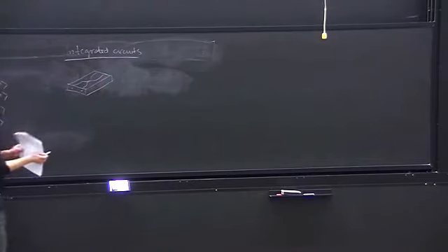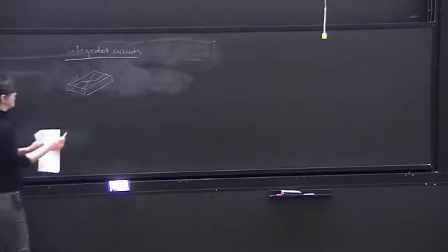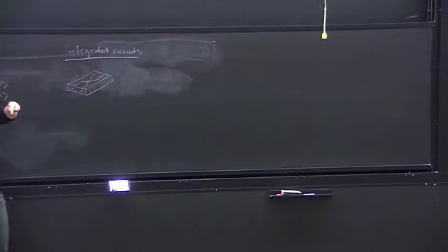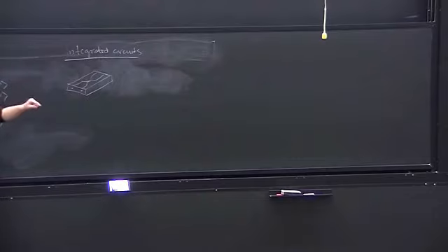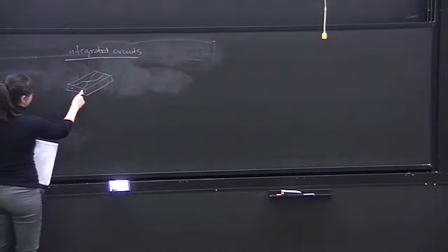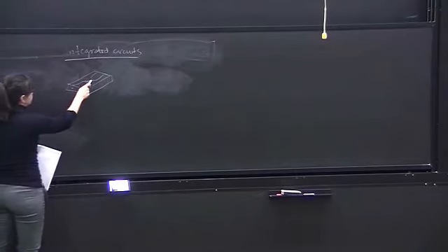The way they build them is they grow some silica, and then they grow just something that corresponds to the waveguide out of a doped silica, and then again put some more silica on top of it. And so the light comes in and then just gets guided by these modes.